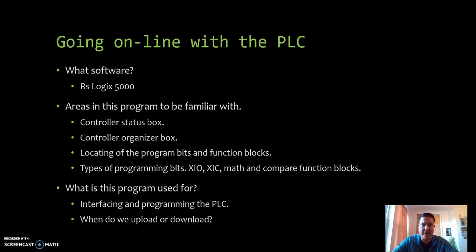The controller status box, which is where we can go online with the PLC. Once we are in that box, we can select if we want to upload or download. We could also change the controller from run mode to program mode and control things from there as far as if the controller is looking for inputs and outputs or the status of the controller. Is it talking? Is it ready to accept inputs and outputs? Is it ready to execute those commands?